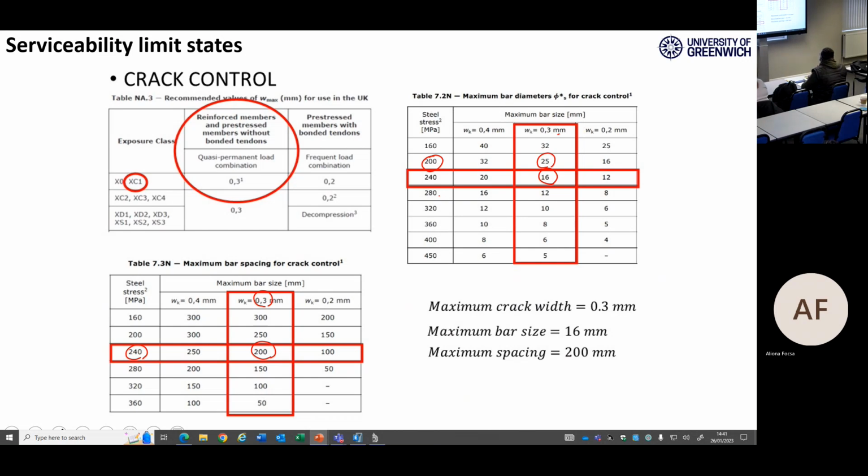For example, if you need to design for the bending moment, you need to design for the shear force. But when you want to select your reinforcement and the spacing between them, you need to be careful about the crack problem. Practically, you can do whatever you need to do, and at the end, just check these criteria.